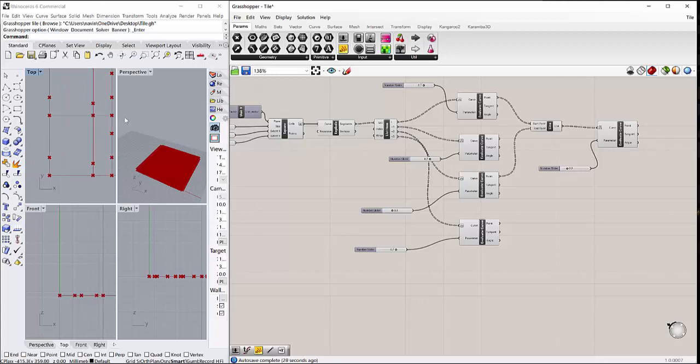Now the next thing I'm going to do is create a centroid. How to do it is simply you select area, because the area has a centroid command. As you can see here, you got a centroid. Now I want to join this point to this point and make a line and do it here like this. Okay, so I'll make that line.